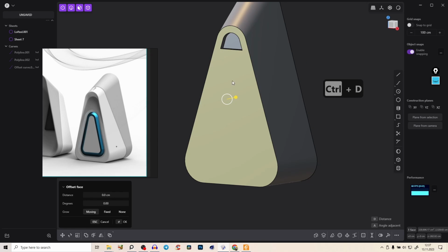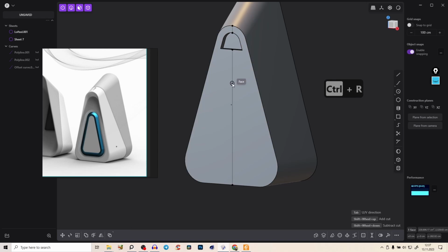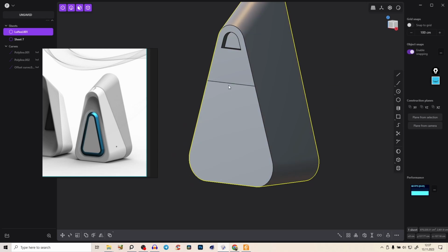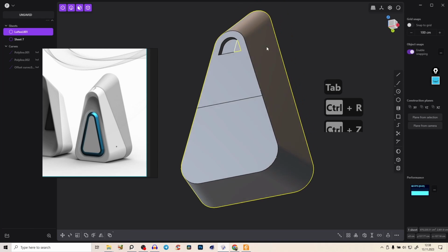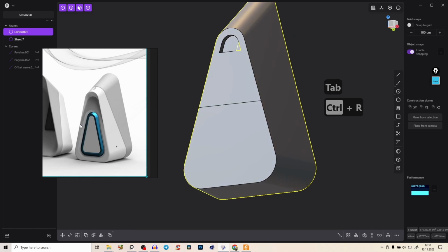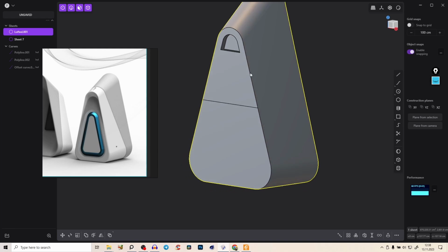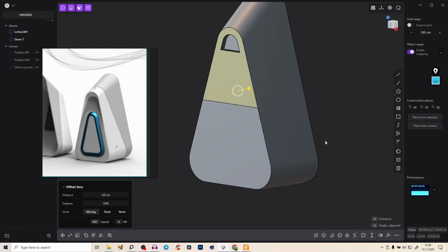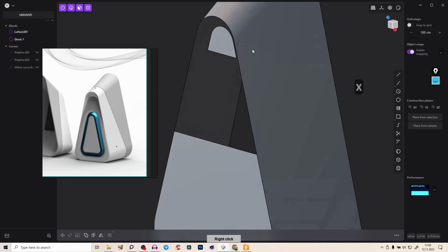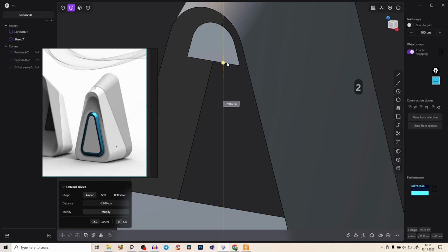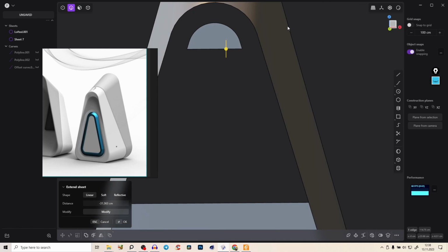And let's add one more curve here. So select that face, Control R, add one line here, or no, maybe it even starts earlier. So somewhere here. Yeah, you see, so here this thing starts to go inwards, because now we can delete this whole face, Shift X, and you see we are getting close. And I also want to make this piece even shorter. You will see why. So something literally like that.